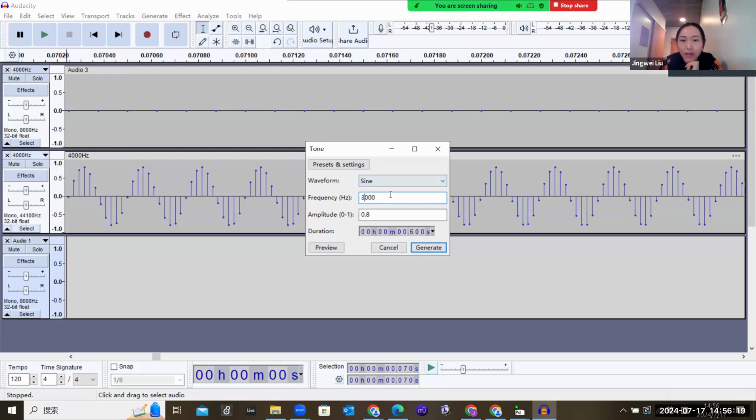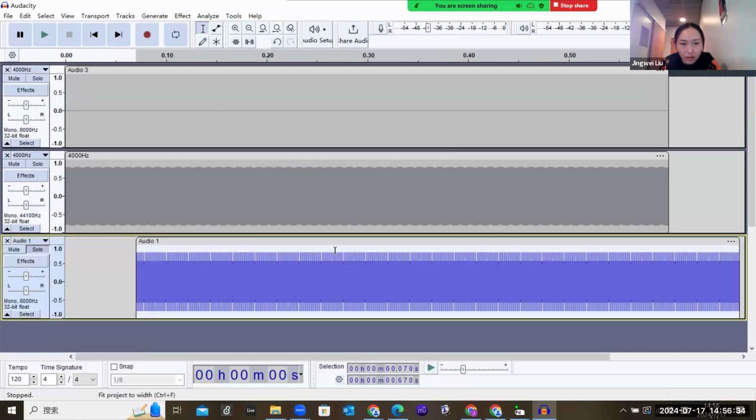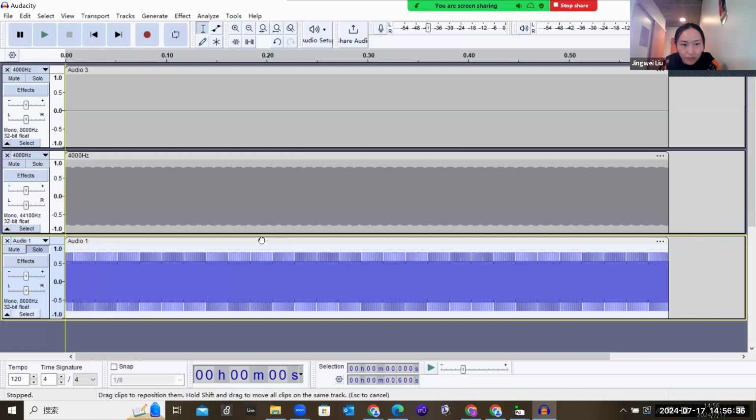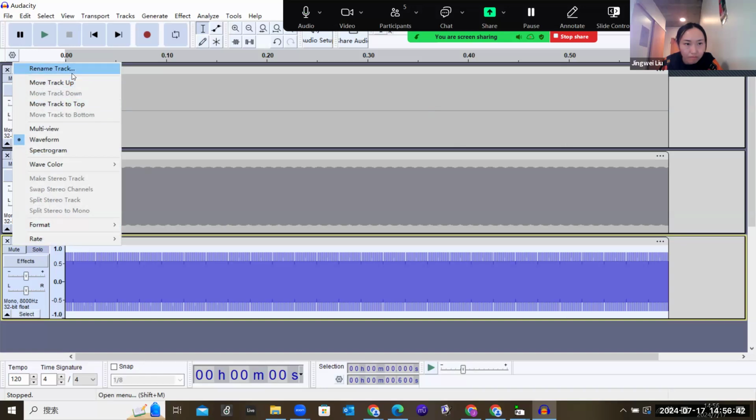So 3,000 is lower than half of the sampling rate, lower than 4,000. Therefore, it should be a faithful representation of this sound. Let me solo this and play this tone. Okay, so this is a 3,000 Hertz tone.